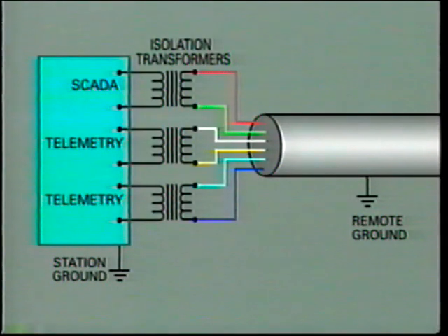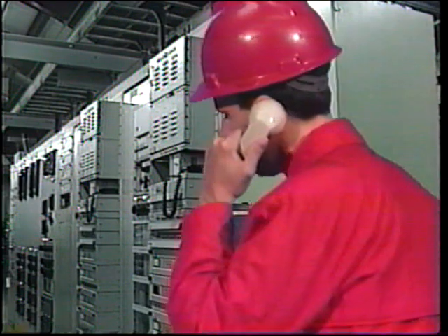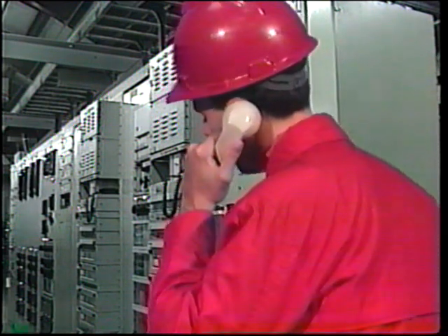This type of protection is very satisfactory, except for the fact that it cannot be used where DC signals are required. As there is no metallic connection between the two sides, DC signals cannot pass through the transformer. This is an important limitation because DC as well as AC is necessary for many of our communication circuits. The most obvious case is the voice telephone circuit.